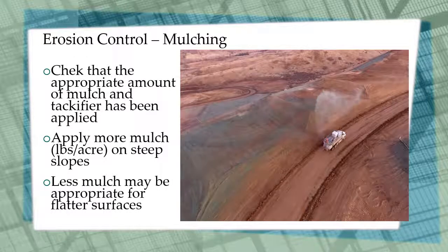Mulching is generally effective for slopes that are steeper than 3-to-1. It's really important that you apply the appropriate amount of mulch and tackifier. More mulch might be required on steeper slopes, while flatter slopes may not need as much mulch.